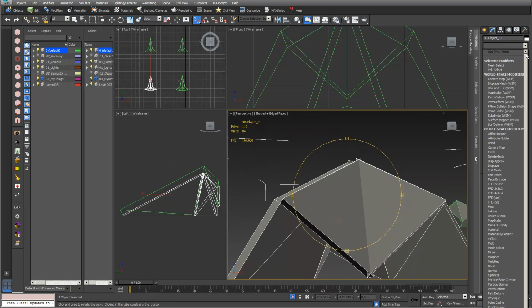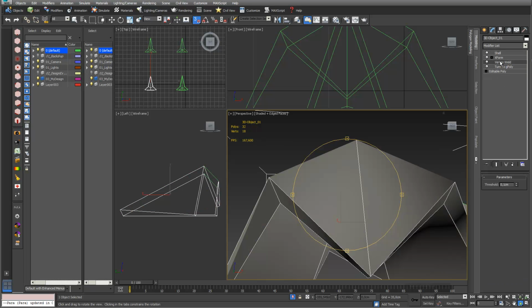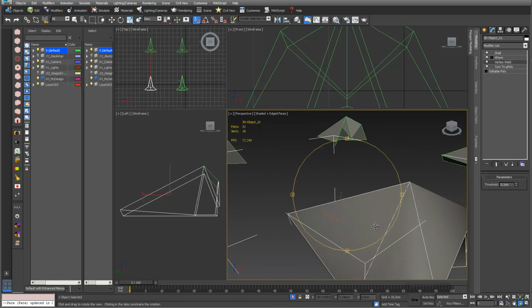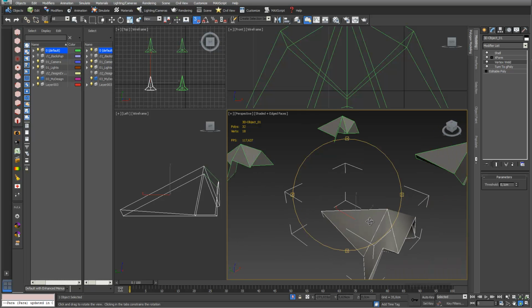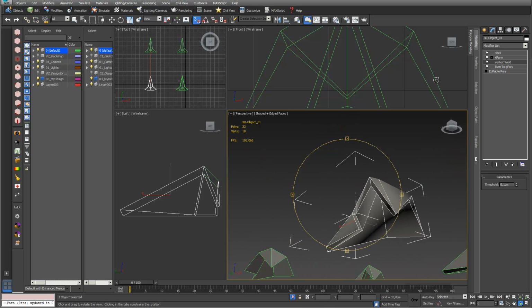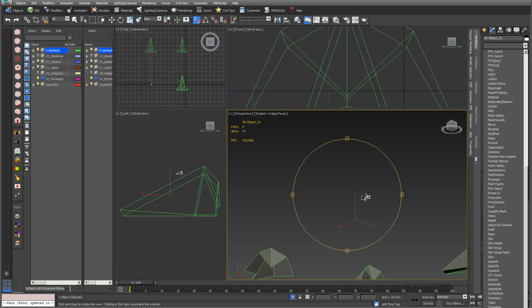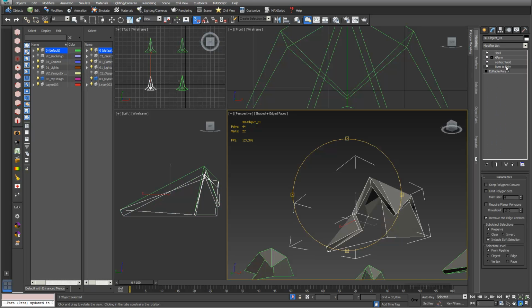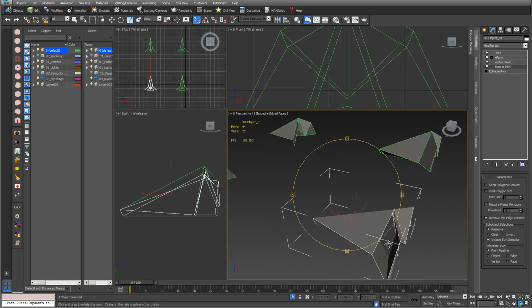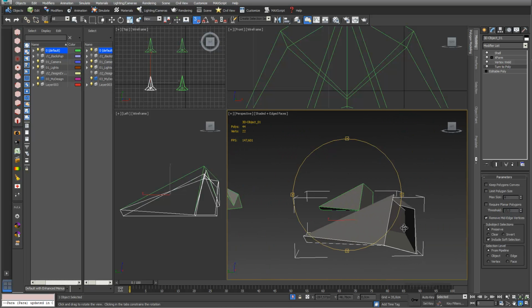And if I put this Vertex Weld underneath, then you can see that it works really well, and we really needed this Turn to Poly and Vertex Weld to make this happen properly. By the way, I normally don't use Turn to GPoly, I just use the modifier Turn to Poly, and this already looks quite good.